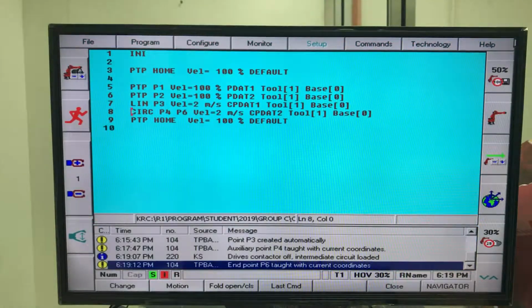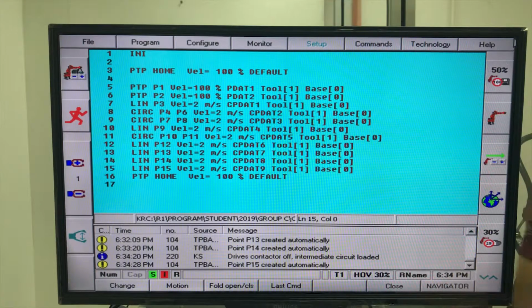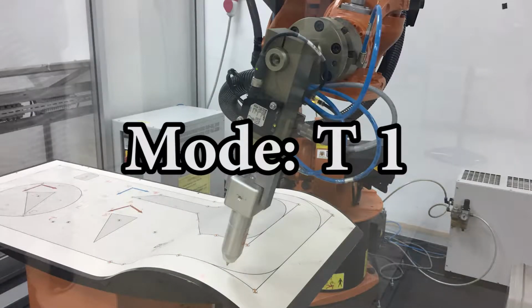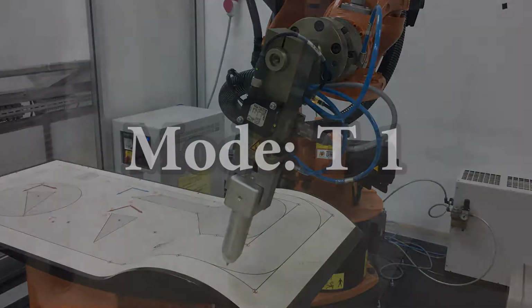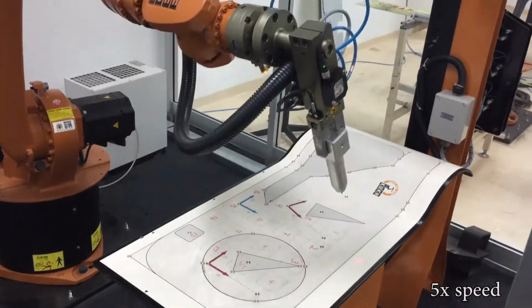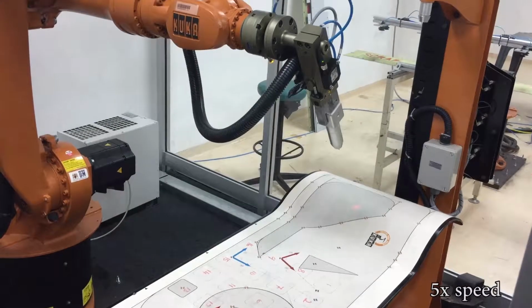The procedure is repeated using circular and linear motions to travel along the contours. Testing of program. In order to verify the motion, the program is run in manual reduced velocity, which is the T1 mode. The speed can be set to 100% because of the lower mode speed.